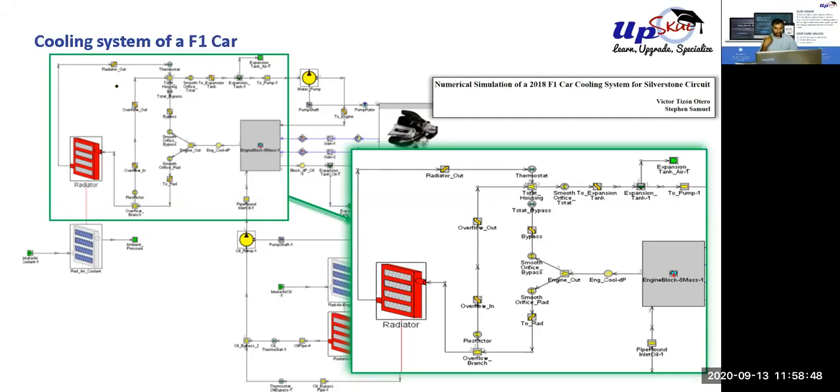But the sports cars that I have worked with sometimes have 7 or 8 radiators, because we have very big engines, 4 or 5 times bigger than the F1 engine, and we need to cool them down. That needs a big radiator, but on a stylish sports car we cannot fit a lorry-size radiator anywhere. So we have to split it into small radiators and position them. Maybe you have seen cutouts behind the door on some sports cars, and strange sized or shaped cutouts on the front side also.